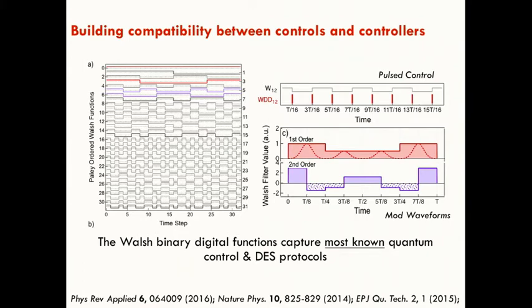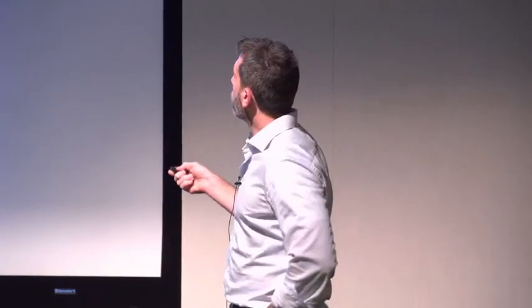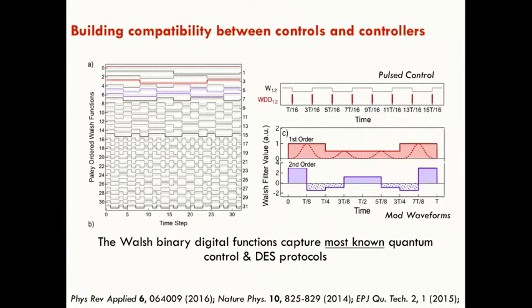The idea is in the architecture, you separate the generation of your high spectral purity carrier, like a 12.6, from whatever does the modulation. So each segment in this gate, so this is a gate that applies a pi rotation of the qubit, right, a bit flip, each segment is a Gaussian. It can be square, or it can be a Gaussian. And that's easy to engineer in anything. But Walsh synthesis then just tells you what the relative amplitudes of those Gaussian segments have to be. You can replace them with trapezoidal functions. You can replace them with anything. The optimization values of what the Walsh synthesis will be will change, but you can still always synthesize in Walsh functions.